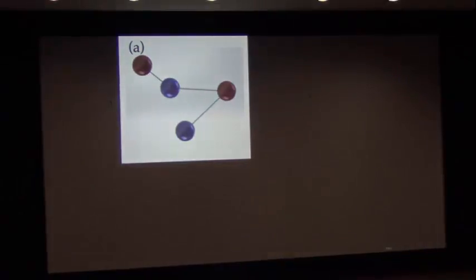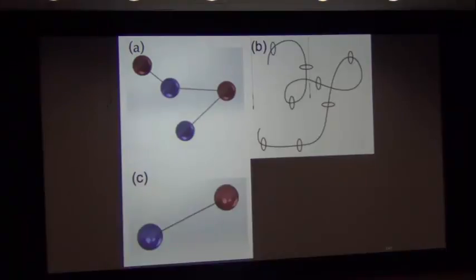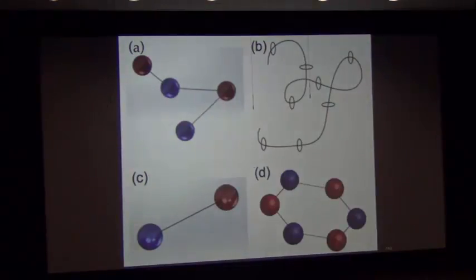Here, for instance, is a chain model where the angles here can move freely, but the distances between the beads cannot change. And for instance, the Curtiss-Bird model looks like that. If you prefer to think of an entanglement theory, then you might think of slip links. And here's another model that has been evaluated in LAOS recently. I already told you about the work that we've done with the rigid dumbbells, but you can also put the rigid dumbbells in a circle to approximate a closed polymer, you see, and some work has also been done that way.